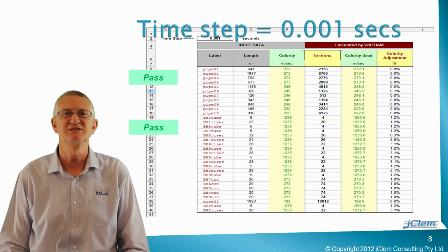In some water system models, users may be able to delete very short pipes without compromising the overall validity of the water system model. For example, it is common to omit the suction and delivery pipes in a pump station and represent these assets just as nodes on each side of the pump.